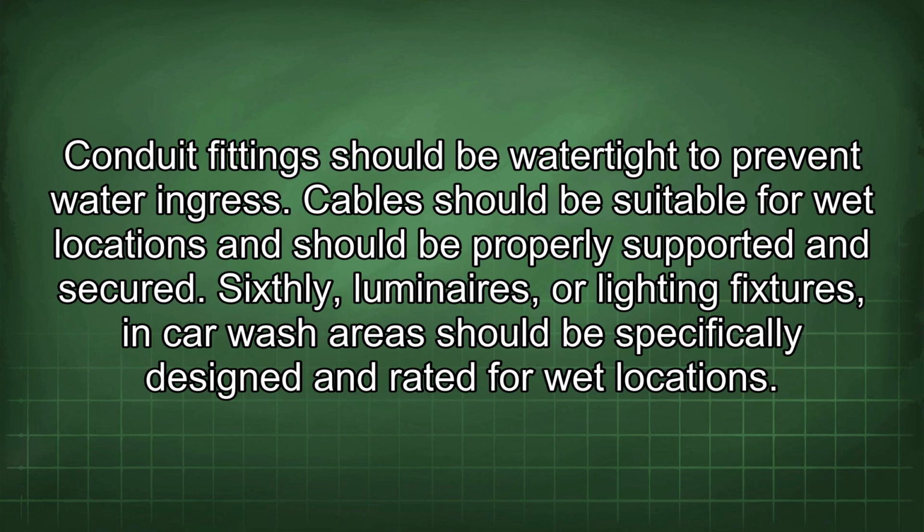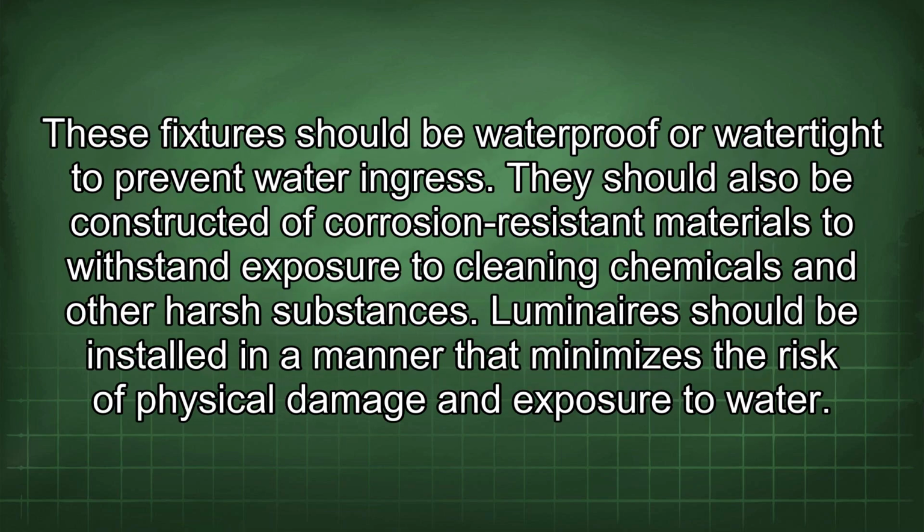Sixthly, luminaires, or lighting fixtures, in car wash areas should be specifically designed and rated for wet locations. These fixtures should be waterproof or watertight to prevent water ingress. They should also be constructed of corrosion-resistant materials to withstand exposure to cleaning chemicals and other harsh substances. Luminaires should be installed in a manner that minimizes the risk of physical damage and exposure to water.